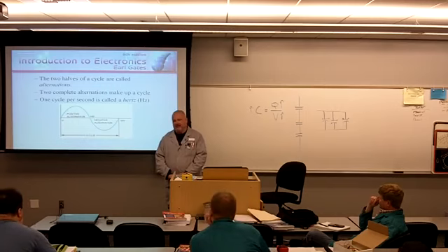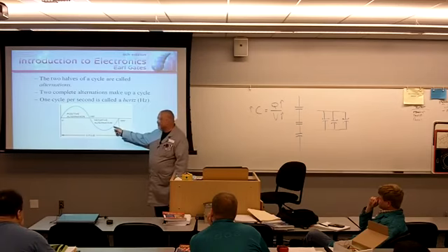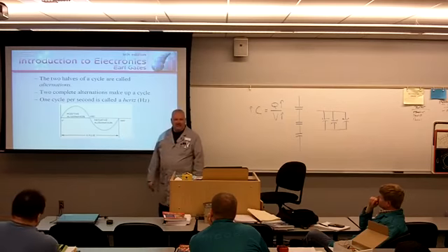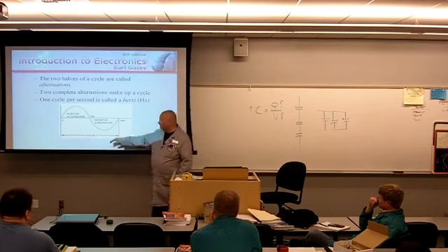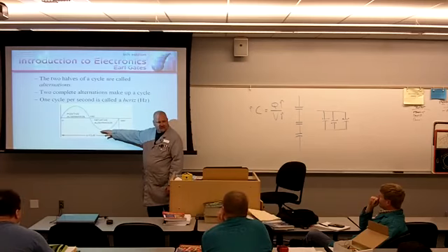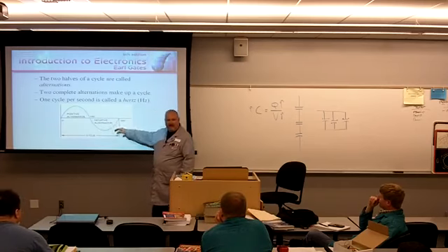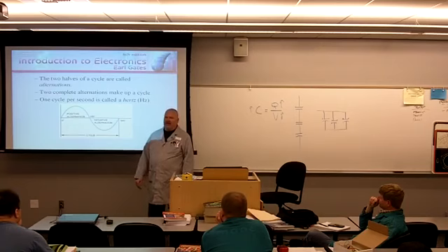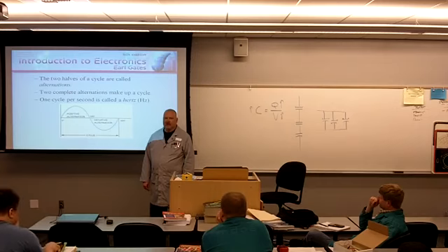Isn't that the bomb? I could say, what voltage is present at 337 degrees? You could plug in sine of 337 and that gives you the percentage. You're obviously going to have to know what this peak value is. Peak multiplied by the sine of that value will give you the multiplier. Did any of you realize this prior to this lecture? Kind of cool, ain't it?